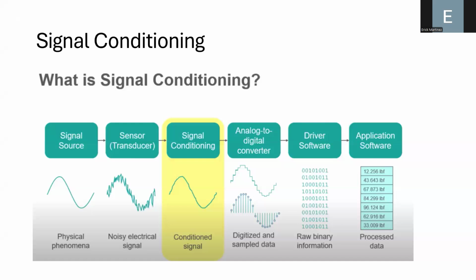In order to amplify the level of voltage of the signal, you need to use a device that is called the operational amplifier. And for example, if you have used these sensors, these cells that allow you to measure the load or the stress in an object, they are also susceptible to noise. You can use some filtering to remove the noise, but also amplify the signal.